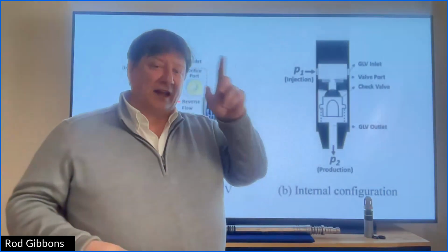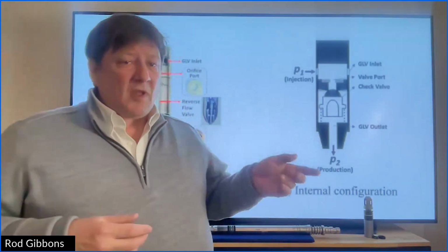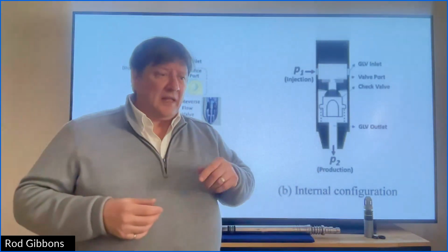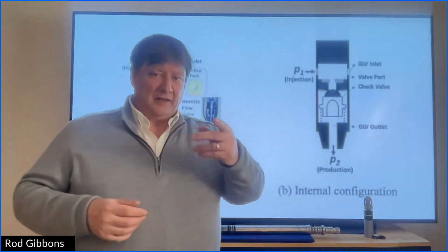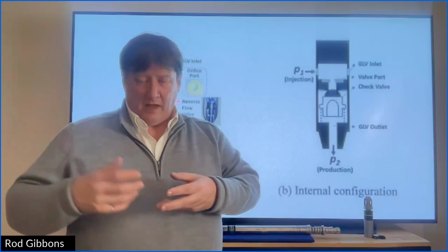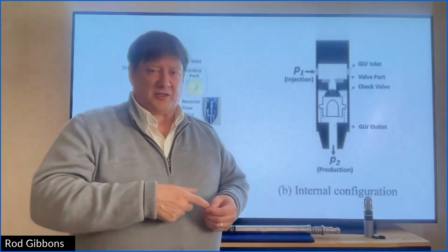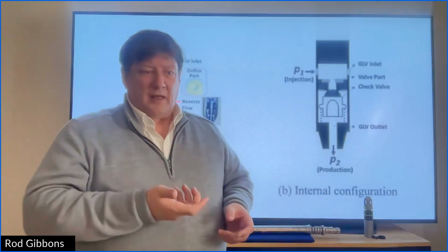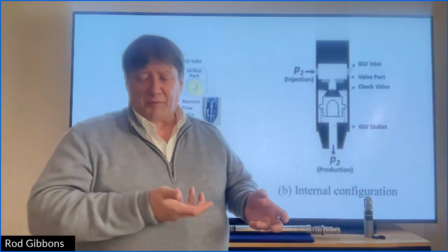So we're recycling that gas when it's on gas lift. And for an electric submersible pump, now we're actually taking that gas, burning it in a turbine and generating electricity with it, and then using the electricity to drive the electric submersible pump.